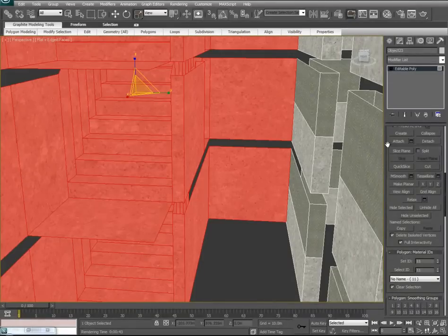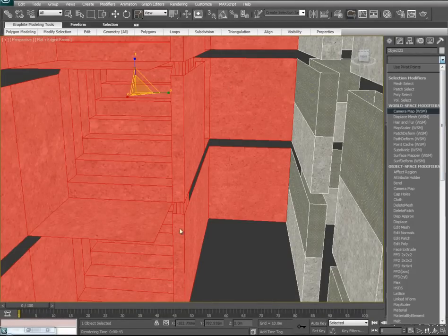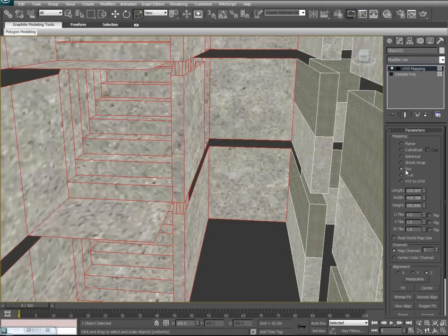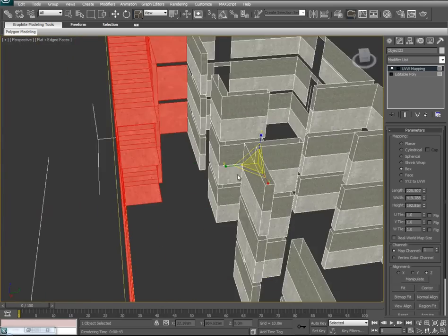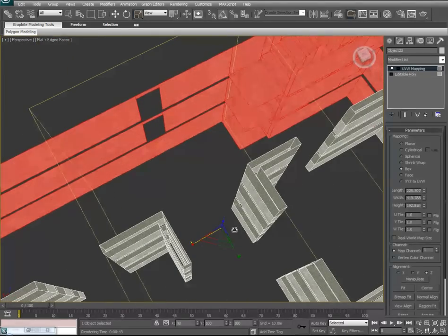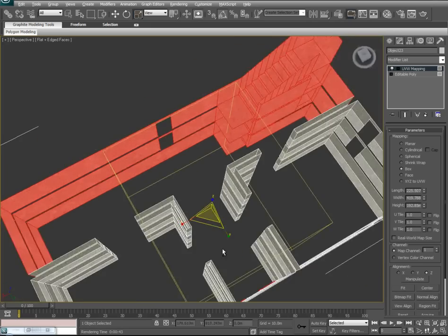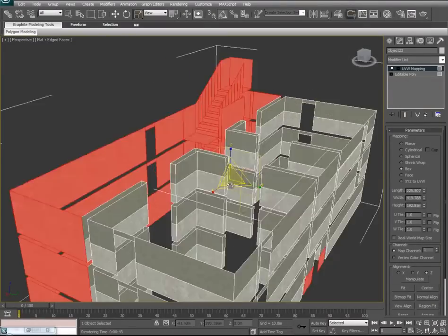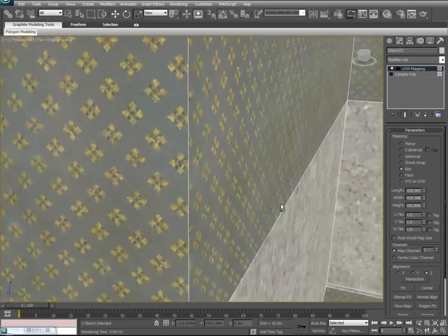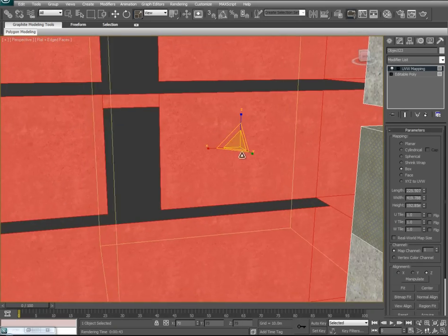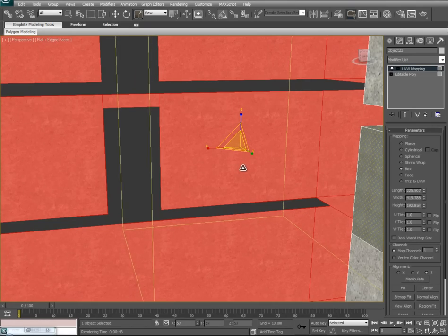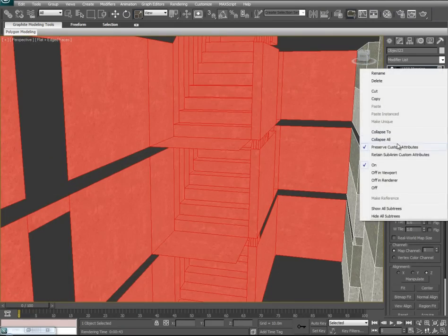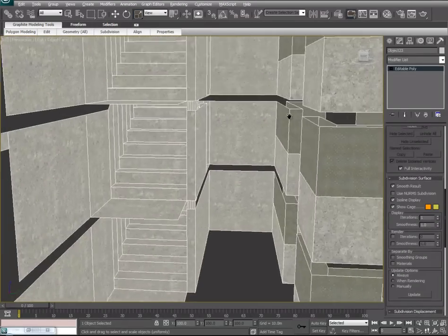For the interior, however, we picked up the same UV resolution as we did from the outside for our main texture that we set up on all the walls. So we'll add yet another UVW, set it to box, and scale it accordingly. And bring its resolution into something that would represent the finer detail of the interior versus the rougher, less resolution detail of the exterior. Collapse 2. And there we go.